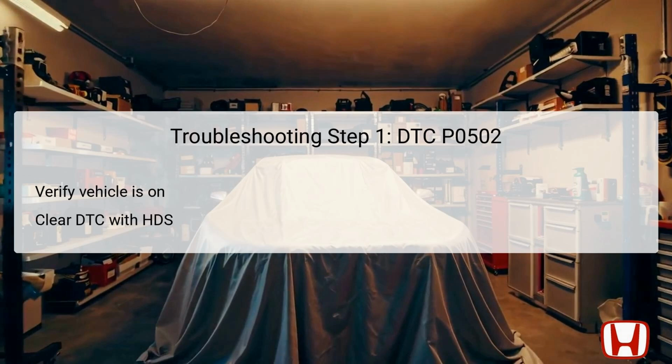Following this, the next action is to clear the DTC using the Honda Diagnostic System, HDS. Clearing the DTC essentially resets the system and allows any current issues to resurface, providing a clearer picture of whether the fault is intermittent or persistent. It's important to note that if the DTC reappears after this clear procedure, it indicates that there is a root cause that needs addressing. At this stage, ensuring that all connections are secure and there are no signs of corrosion is also a good practice before moving to subsequent troubleshooting steps.